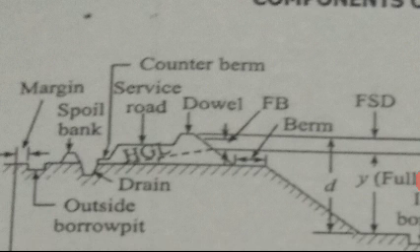Dowel or dowla is a protective small embankment which is provided in the canal side of the service road for safety of vehicles plying on it. It acts as a curb of the inspection roadway towards the channel. Its level is above FSL. The top width and height above the road are kept normally at 0.50 meter. Side slope will be same with main bank.